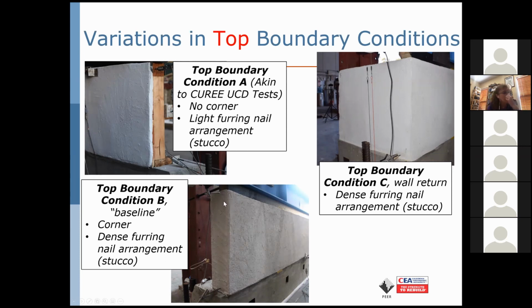And they suggest that a more robust nailing arrangement at a top plate, namely a triple top plate, that doesn't show this here. You're seeing the finish, the stucco finish face, but you can see the dramatic difference in the wraparound of the stucco comparing this upper left figure and this lower figure. That's intended to emulate the continuity that would be present in the typical cripple wall.